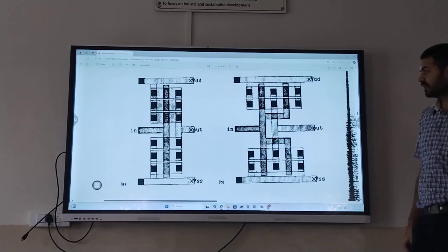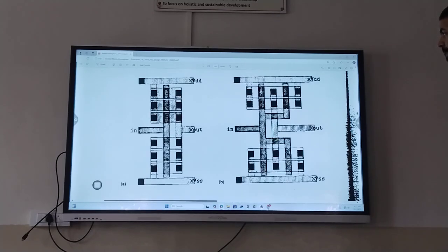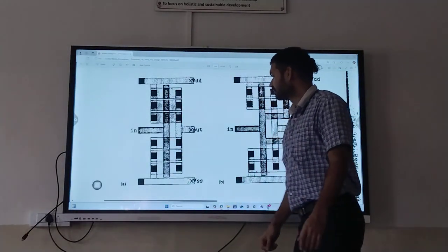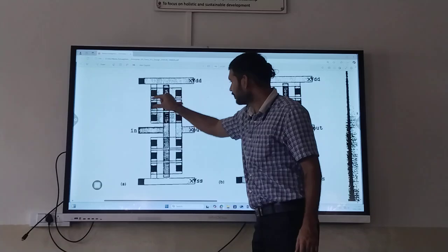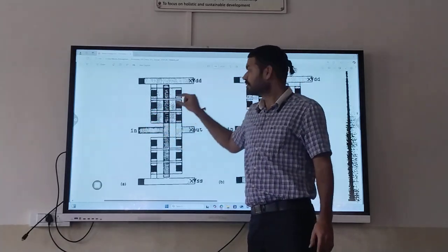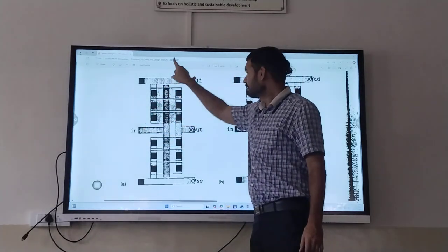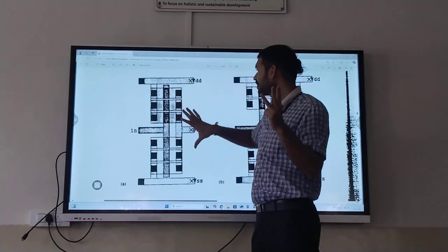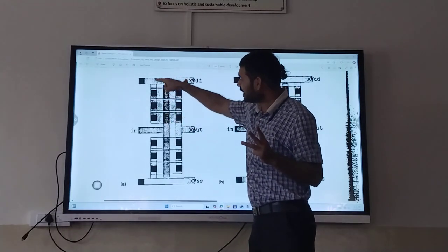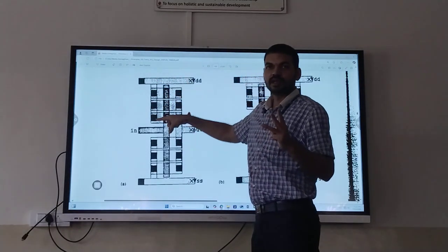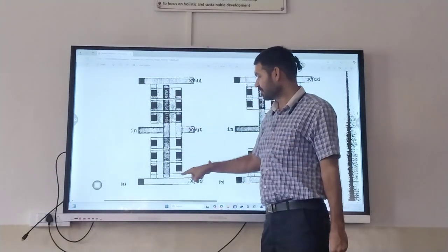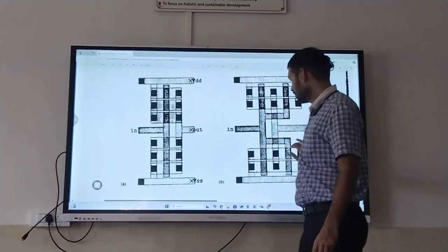So in this, how many inverters are there? 3 inverters are connected parallelly. P diffusion, P diffusion, P diffusion. P diffusion, P diffusion, P diffusion. One poly. So yes, transistors form on the 3 P MOSFETs. Okay. And see the connection. VDD is shorted to all the sources. And here all the drains are shorted to all the drains of NMOS. So here this is parallel inverter.